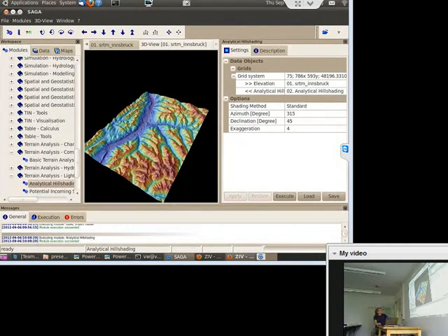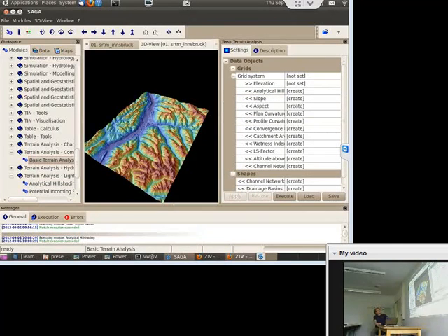It's called basic terrain analysis. It has a lot of parameters because it's simply coupling all these modules. Instead of scripting this, it is very easy to program such meta modules in SAGA. It's done in C++, but you just provide calls to each module and provide the parameters you would like to use. So in our case, we simply select the grid system again and provide our elevation data set as SRTM